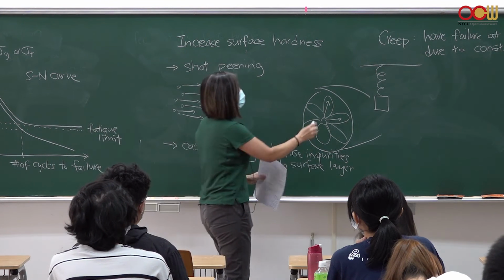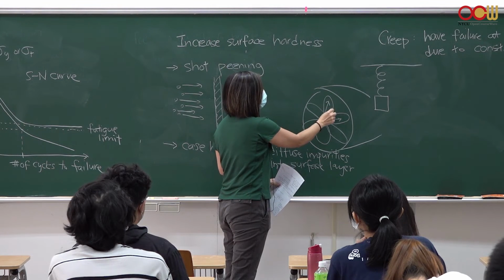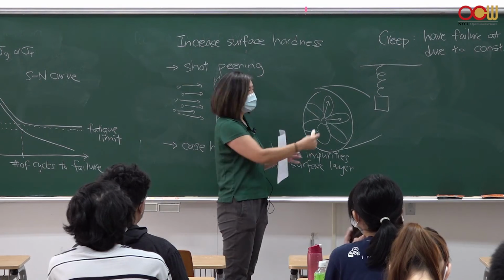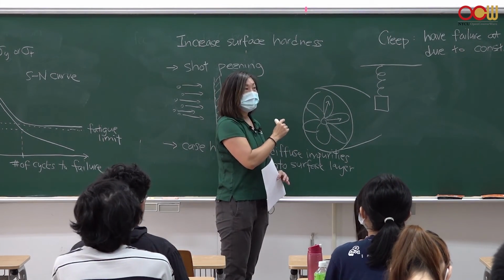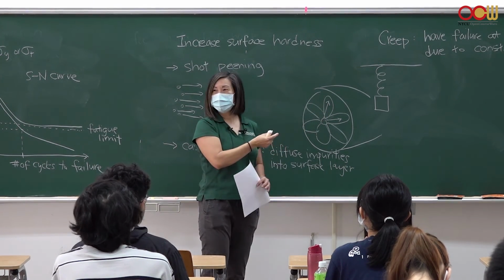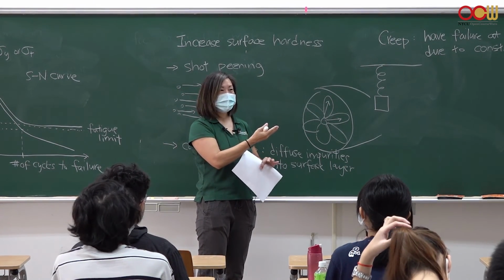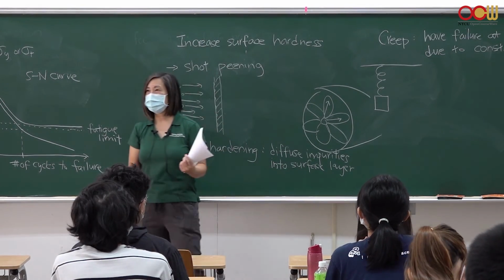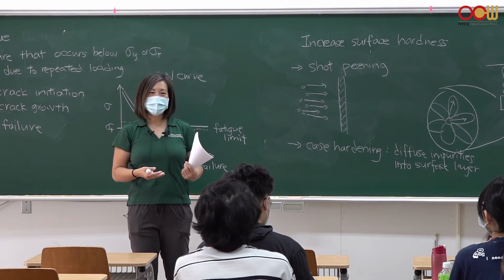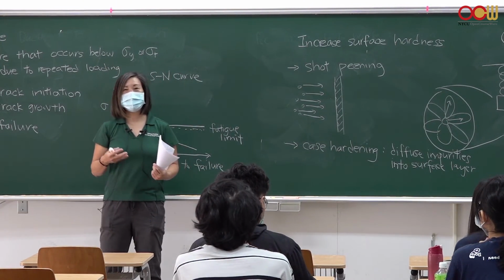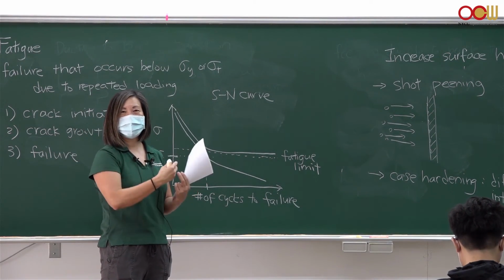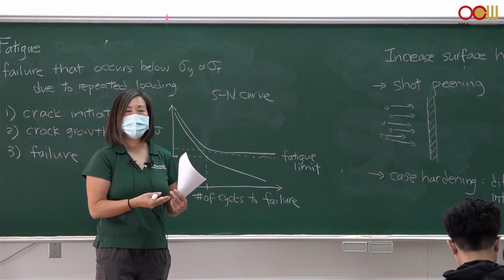And turbines work only if the blades are very, very well fitted to the outer layer. It can't have too much of a gap. So if there is creep, that means the material starts to elongate. It will hit this outside, and the entire turbine will experience catastrophic failure. So it's really important when looking at turbines to make sure that the material does not experience creep, because any elongation in that turbine blade will cause the entire thing to fail.